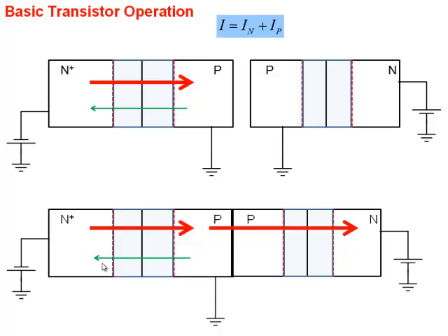And in addition, I have these holes here. What other current do I have? I will have some small number of holes coming over to this side, and I've neglected it because it's a reverse bias junction. So that's the picture of current for a bipolar transistor in which the emitter-base junction is forward biased, that you see here, forward biased emitter-base junction, and the collector-base junction reverse biased.